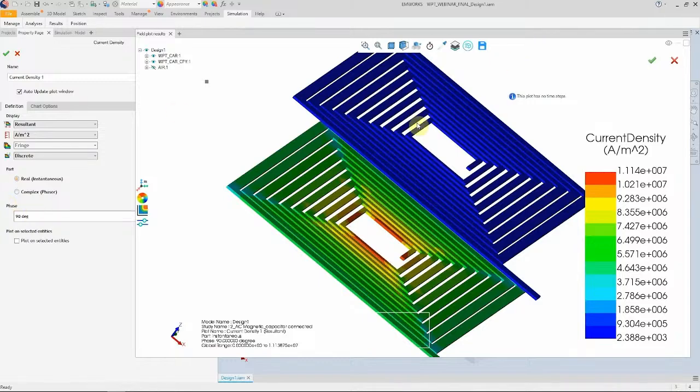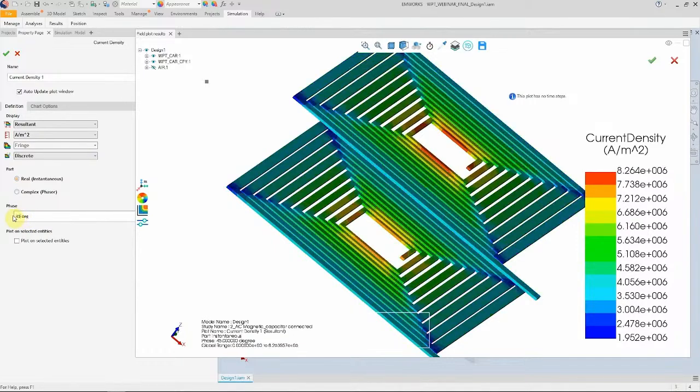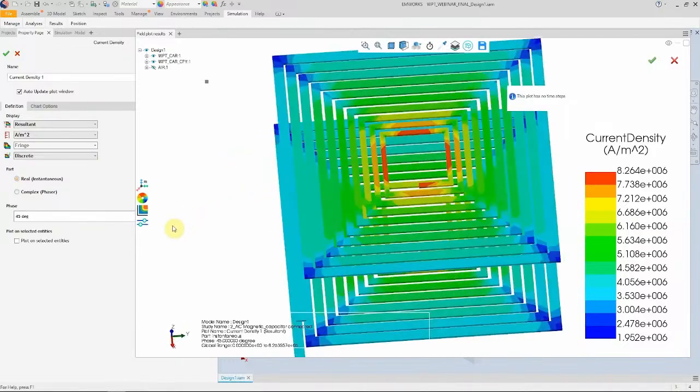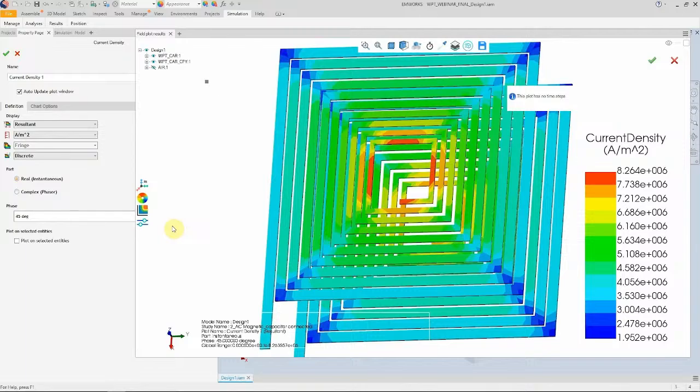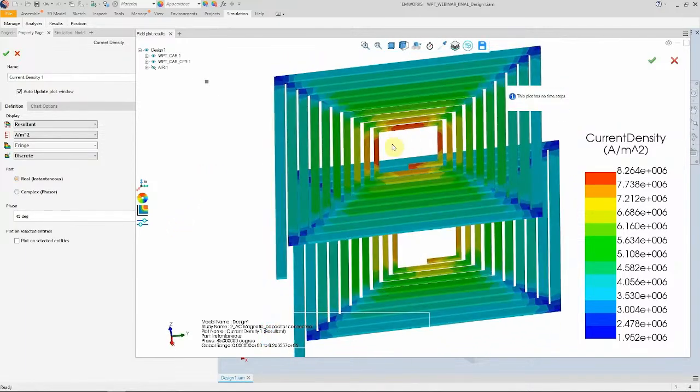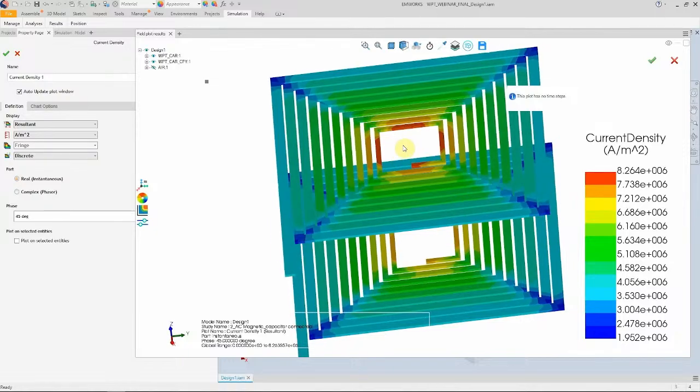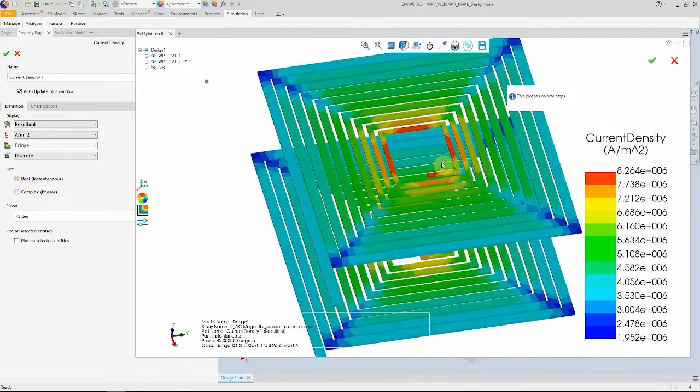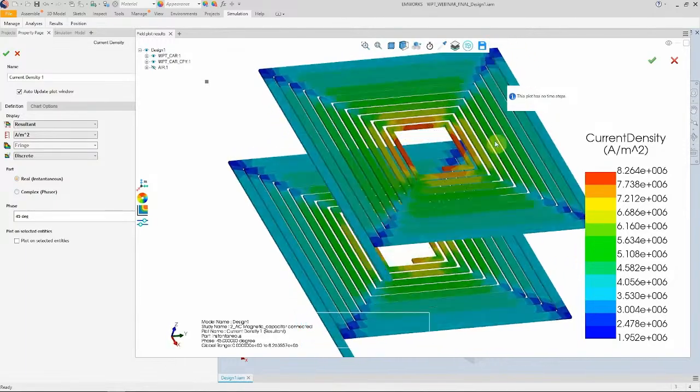In 90 degree, as we injected the sinusoidal waveform inside the first coil, the value of the current will be 0. But in 45, I think the values should be almost the same. With plotting current density, you can find the hot spot, the places that you need to change the diameter or distance between coils, and you can measure the skin effect or proximity effect in the windings.